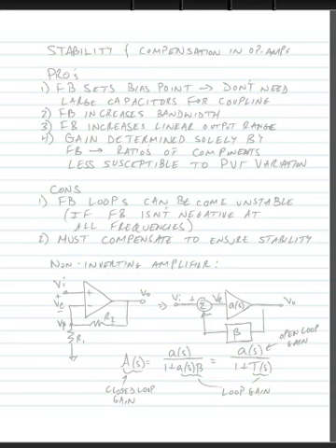In the last lecture, we found out about slew rate in operational amplifiers, and that the slew rate is typically determined by the compensation capacitor chosen and the amount of current that you desire to burn. In this lesson, we're going to start talking about stability.